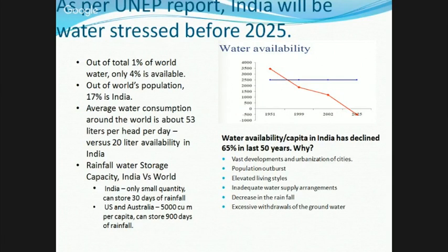The water table in 1990 was 20 meters, and in 2000 what we observed was 80 meters. So in 10 years the water table has gone down by about 60 meters. That means 6 meters per year, which is very alarming. If it is going down 6 meters per year, it is on the very higher side.